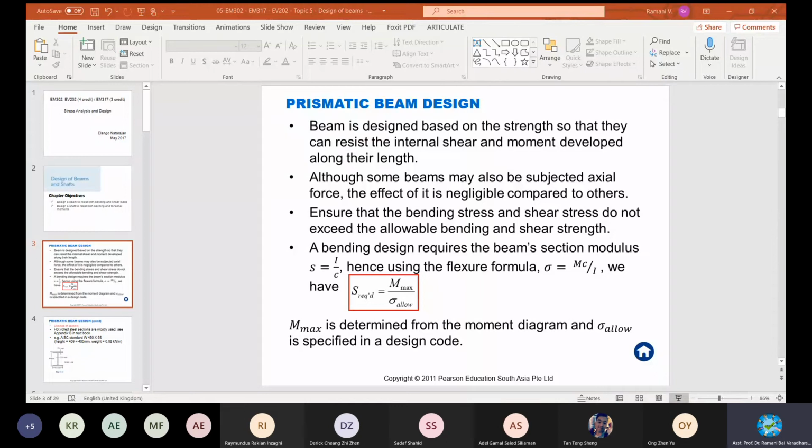I have given you the information about bending. Bending happens parallel to the longitudinal section, and you are going to design for that. You are going to design for the allowable value, which means the factor of safety will always be more than 1. You're not going to design for a failed member, right? In that case, you can still use the flexural elastic formula within the elastic limit. That means you are designing within the elastic limit. Still you can make use of the formula that we derived last class.